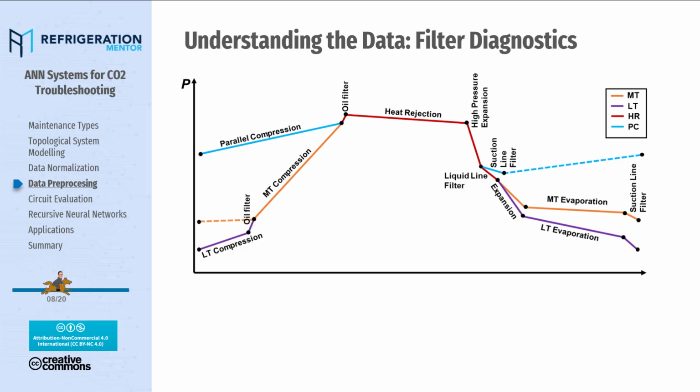In this slide, you will see how the pressure behaves in the system. In theory, pressure drop in the CO2 system will only be in the high pressure valve, the HPV valve, and in the evaporation circuits. But some lines, such as the condenser, or elements such as filters, will have a pressure drop, something that in maintenance can result in a risky situation because of the production of dry ice, resulting in burns and maybe some exposure to the technicians.